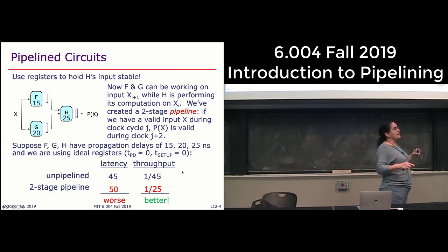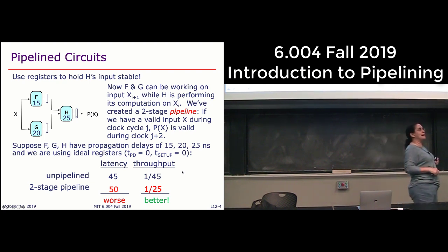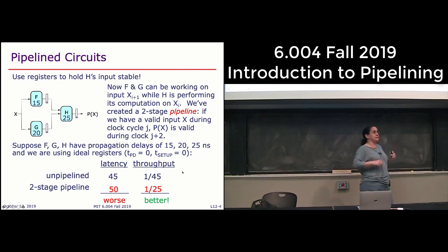So in that first cycle, it'll still take, let's say, 25 nanoseconds. And then after those 25 nanoseconds, I go to my second cycle, and that's another 25 nanoseconds. And so the output associated with input X isn't available until 2 cycles later. So 2 times that clock period.